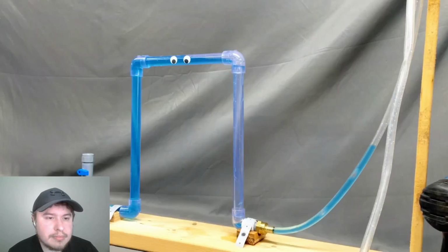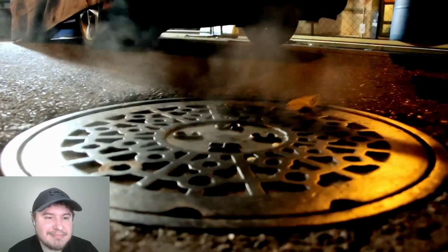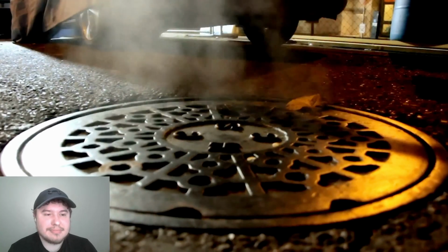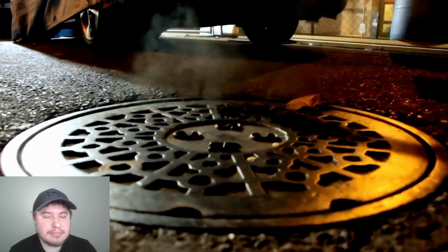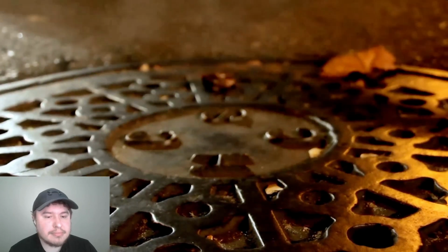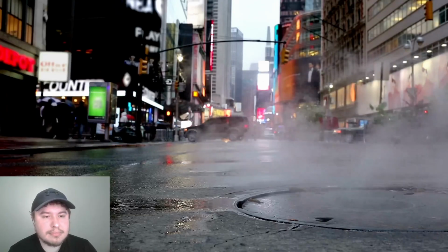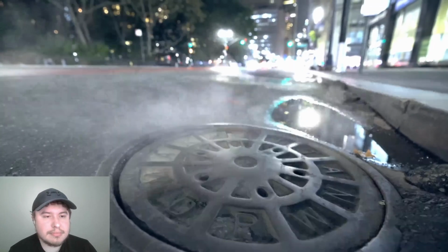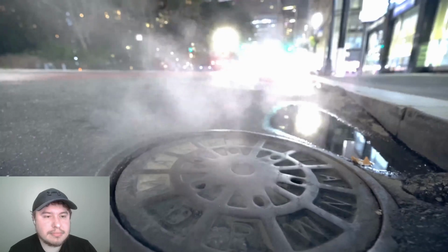Air bubbles can restrict the flow of fluid in a pipe, and air pressure can cause wacky problems like backflow. Along with regular air, toxic, corrosive, or even explosive gases can also build up in a sewer if there's no source of fresh air. So ventilation from manholes is an important aspect of the system. Sometimes you'll even notice condensed water vapor flowing up from a manhole cover. In a few cities, like New York, that might be related to an actual steam distribution system running underground.